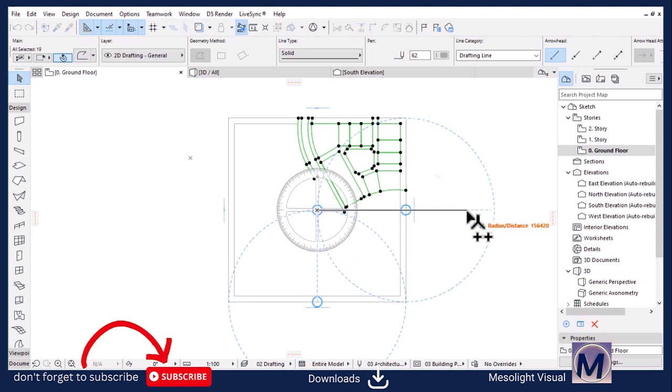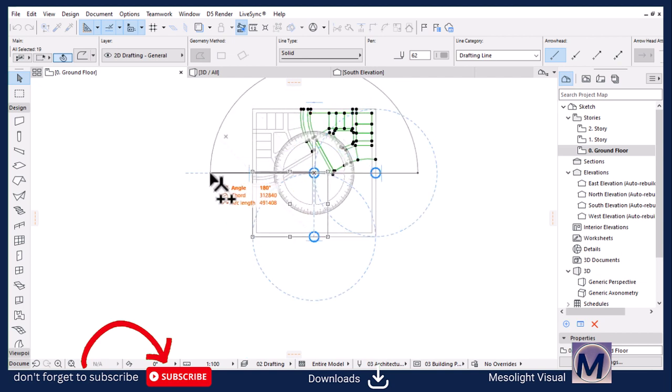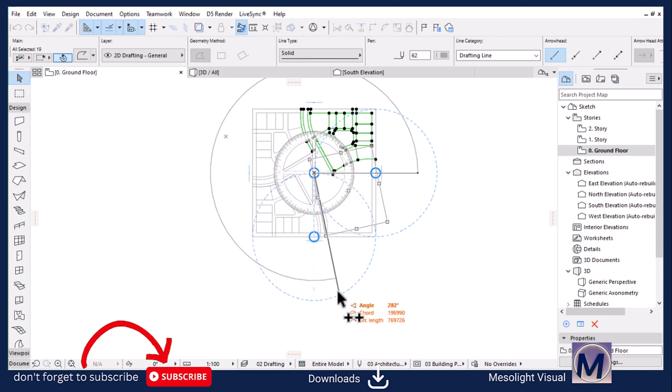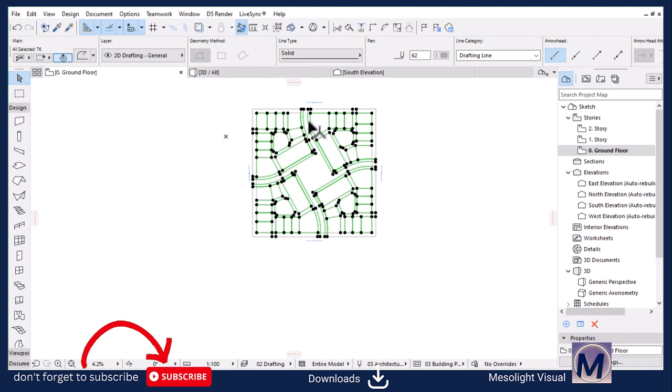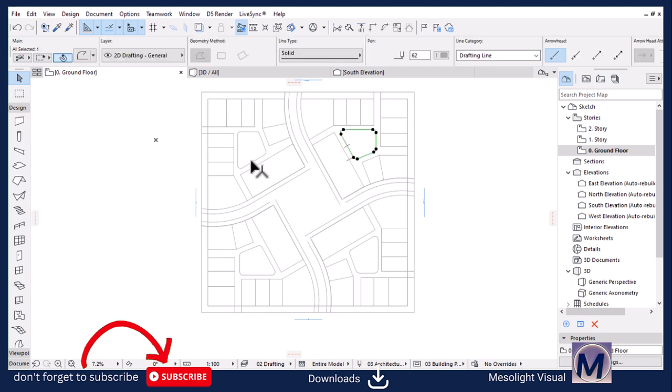So I'm going to start in this direction. I'm going to rotate this by 90 degrees and then do the same to this corner by 180 degrees. Lastly, let's do the last corner, which is 270 degrees, and then again hit escape. Now the site is complete. We have a series of residential plots and commercial plots, as you can see here. The bigger ones are for commercial plots, and then the rest is residential with some open areas, as you can see there.